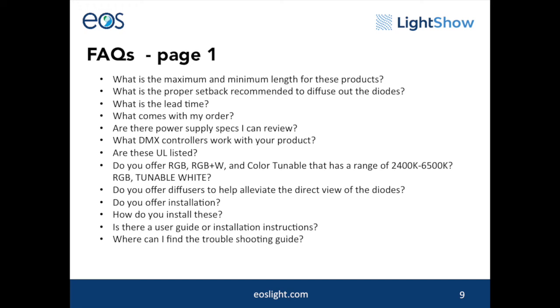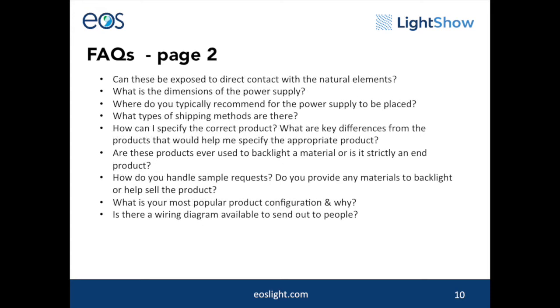Where can I find the troubleshooting guide? All electrical equipment will come with user guides or installation documentation. Copies of the same guides and documentation will be available online. Can these be exposed to direct contact with the natural elements? The LED nodes are IP66 rated, but they are not suited to marine environments or prolonged exposure to salt spray. Vertical strand orientations should be avoided in wet locations. IP66 power supplies are available.